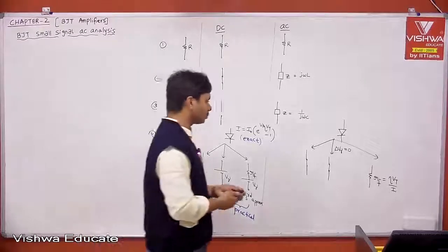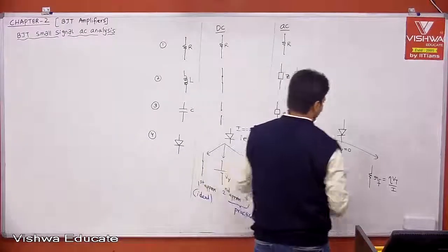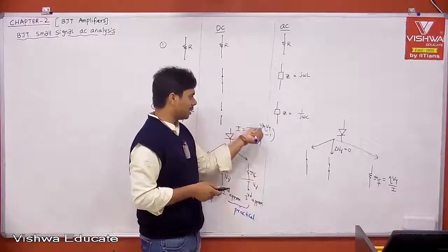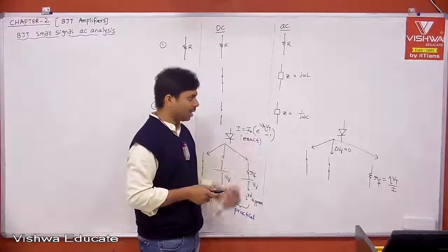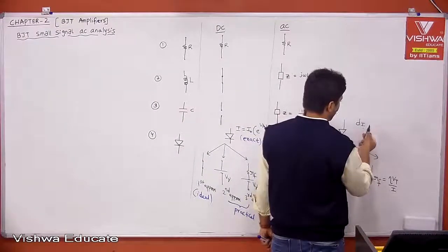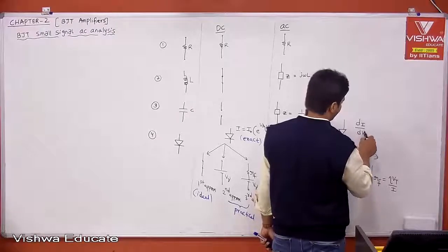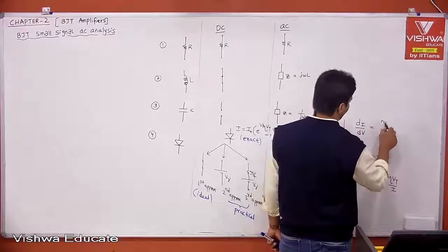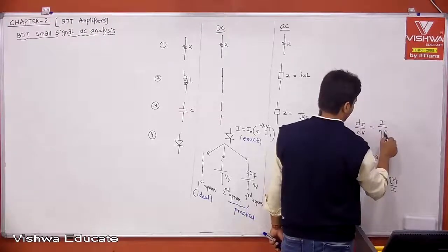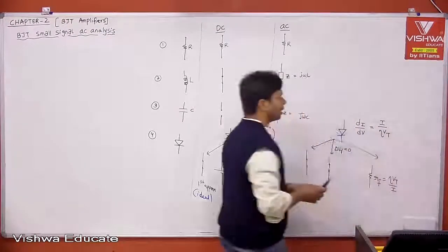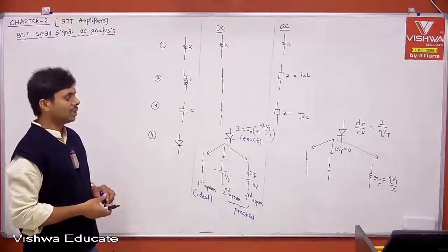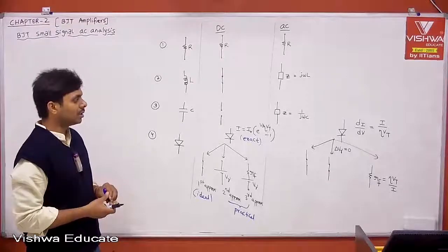Okay. Now, this is what your RF. Now, if I say the DC current equation, now we should not say I is equal to I naught into e to the power V by eta Vt minus 1. Now, we need to take the relationship. Therefore, always represent di by dV. Therefore, di by dV is equal to, we already derived, I by eta Vt. This is the relation. di is equal to dV into I by eta Vt, that is your forward resistance into delta V.